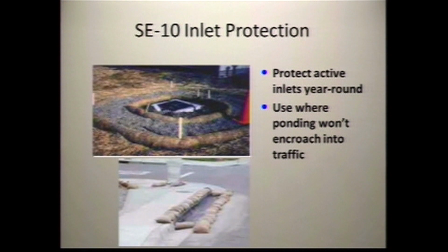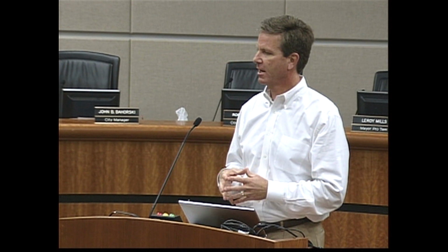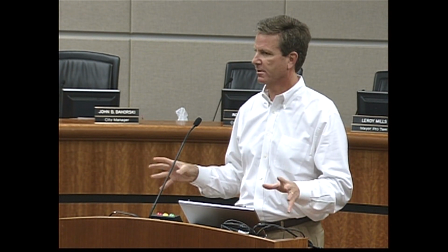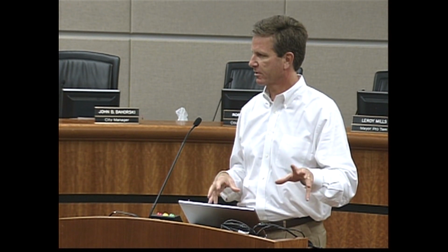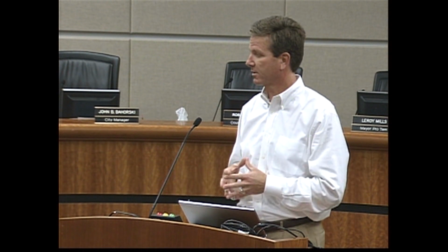And then finally, inlet protection. Same thing. We're stopping the water behind the bags. The particles are settling out. Clean water is bleeding into the inlet. The filter fabric is very good to have during the dry season, but not the wet season. It keeps all the dirt and the trash out of the storm drain system, but you're not going to pass enough water through it during a rain event to keep the inlet from clogging or the filter fabric from pushing through. So just make sure that the fabric's taken up and the bags are what's doing the job when it's going to rain.